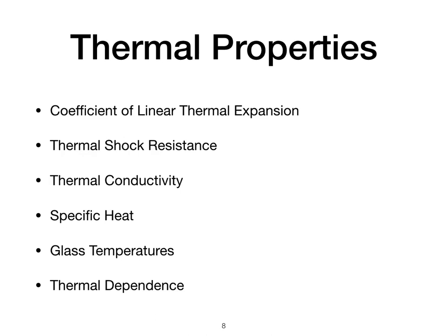Glass temperatures. Some typical five important glass temperatures are often discussed in the production and design of glass. That is the melting point, working point, softening dilatometric point, annealing point, and strain point.